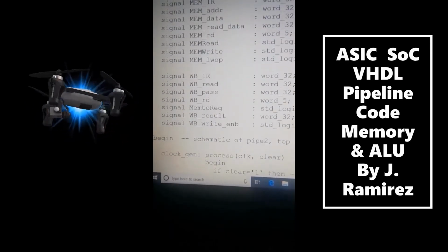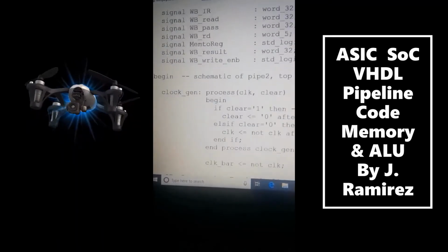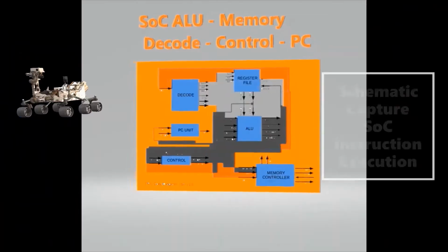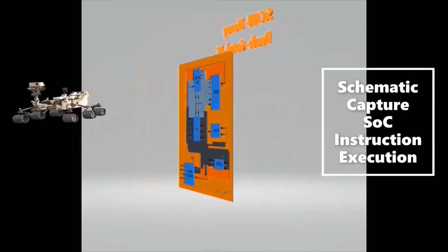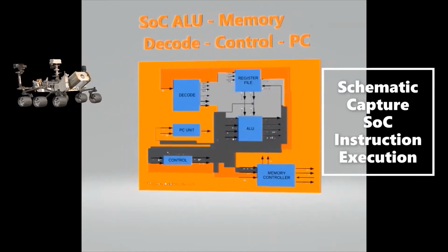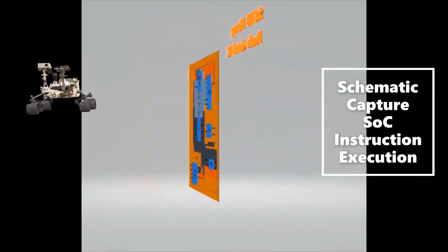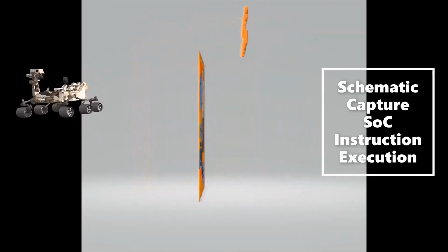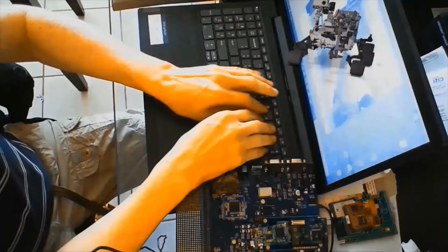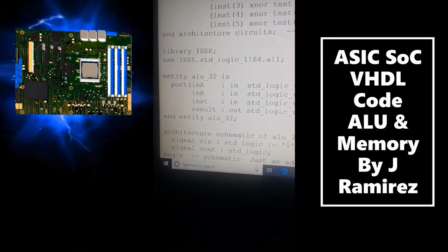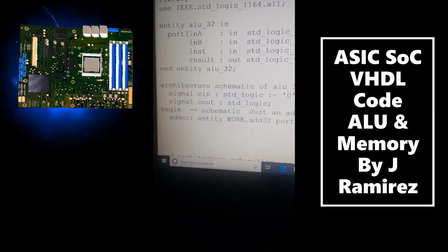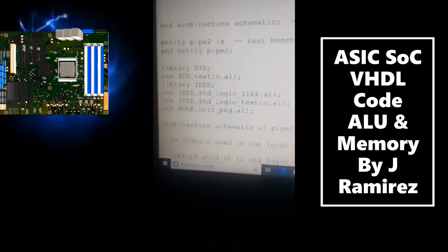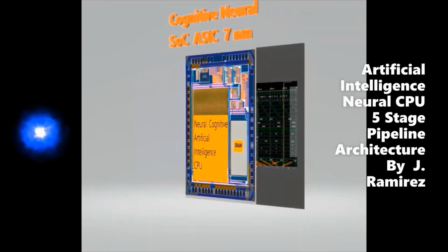The decode stage. In this stage, the processor decodes the instruction to produce the control signals and reads the source operands from the register file. The execute stage: the processor uses the ALU, arithmetic logic unit, or the multiply divide unit to perform required computations, which may be the calculation of values of two registers or address calculations.